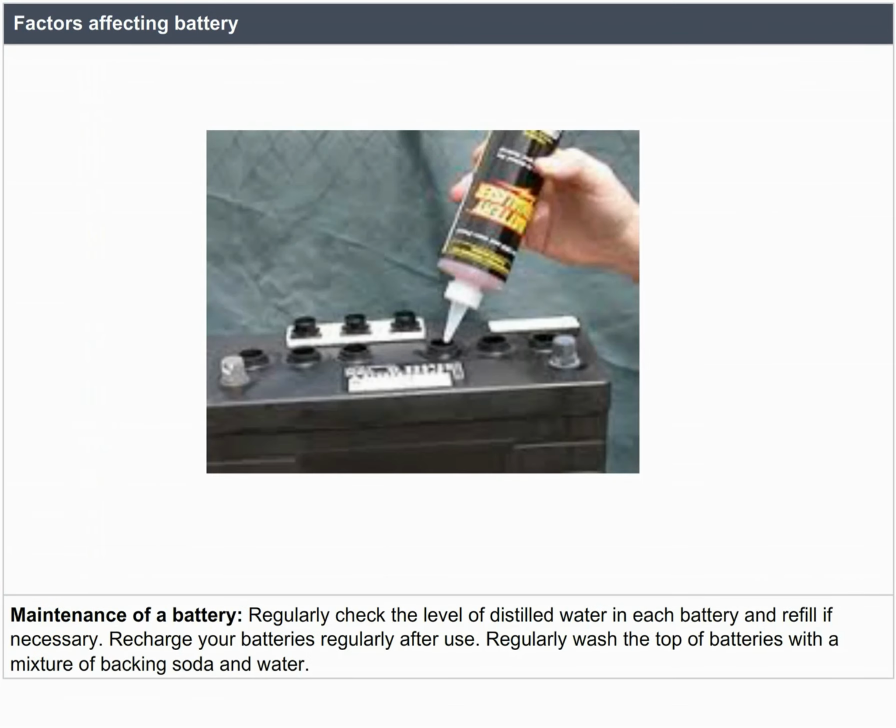Maintenance of a battery. Regularly check the level of distilled water in each battery and refill if necessary. Recharge your batteries regularly after use. Regularly wash the top of batteries with a mixture of baking soda and water.